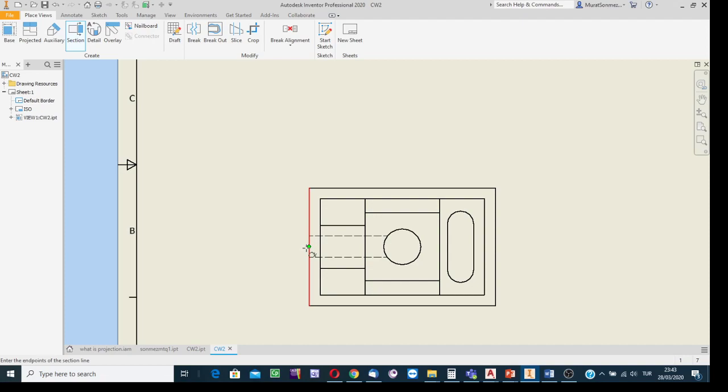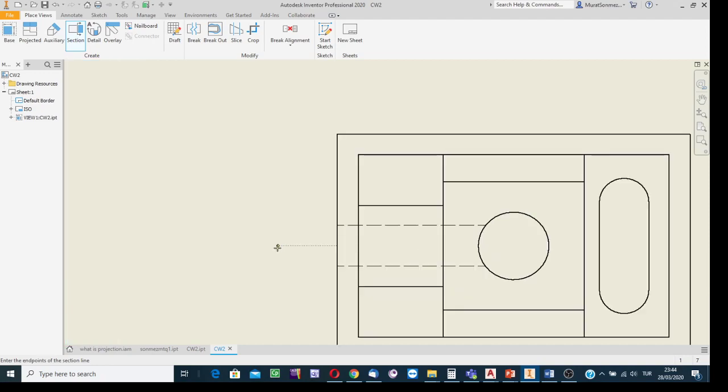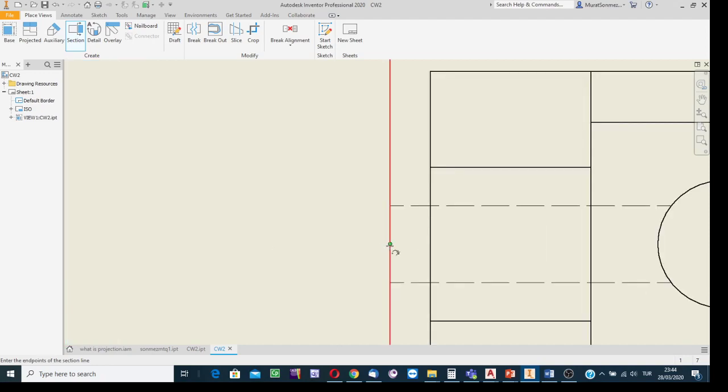In Inventor, highlighting is done by using a little green dot. Okay, don't click but move the cursor away. Similarly, in Inventor, the track facility is automatically enabled. There is no need to click on the track button on the status bar. There is no such thing actually. It automatically distinguishes, that is the purpose, and the cursor is to move along such a track line. The track line appears on the screen. You see between that characteristic point and the cursor there is a dotted line.